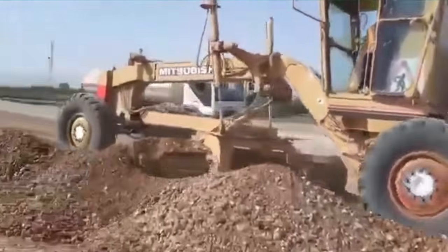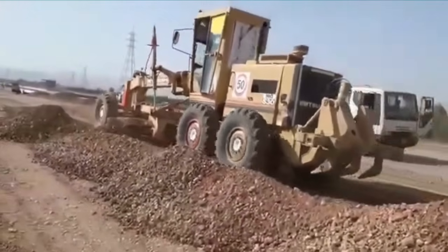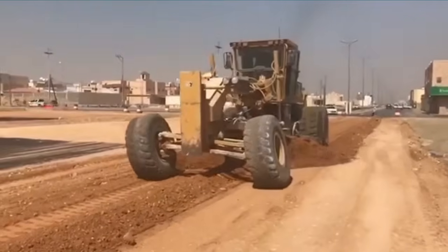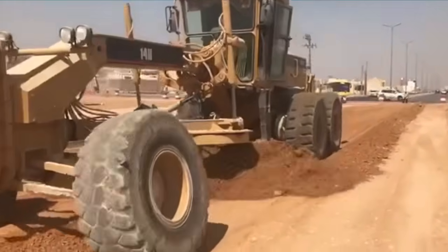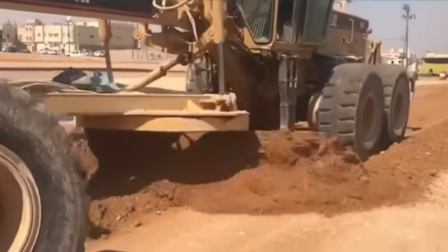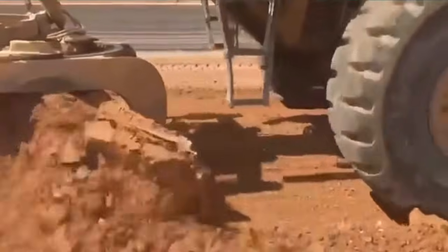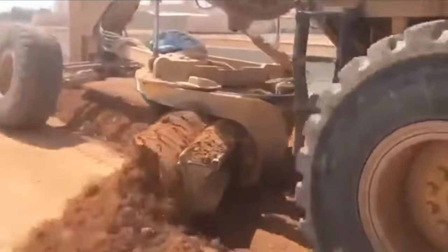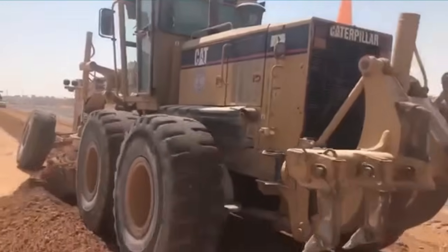The compaction shall be done mechanically, by using vibratory rollers of 80 to 100 kN static weight for the entire width of the pavement. The rolling shall commence from the lower edge and proceed to the upper side, with 1/3 overlap. Generally, 6 to 8 passes are required for compaction of 98% of lab density. Each layer shall be tested by the sand replacement method.